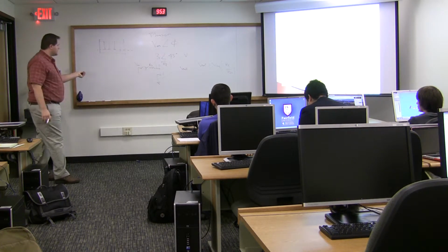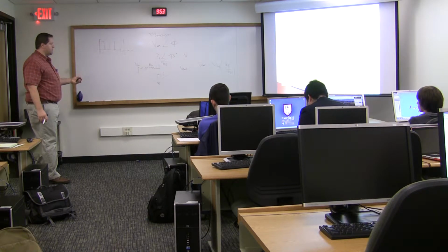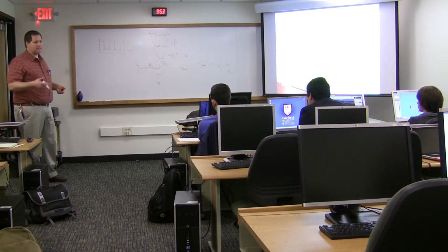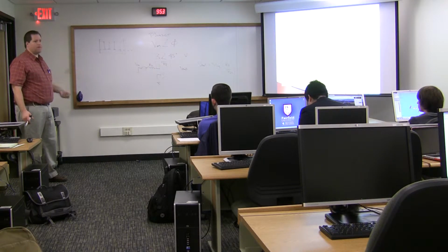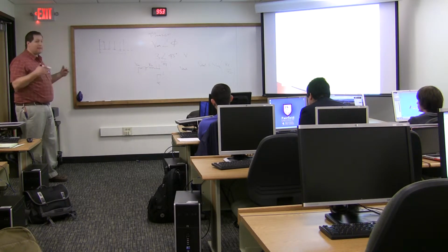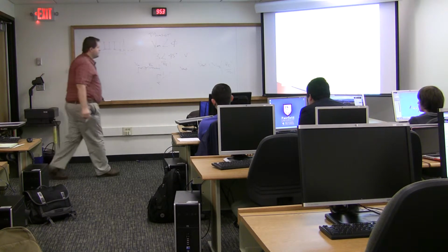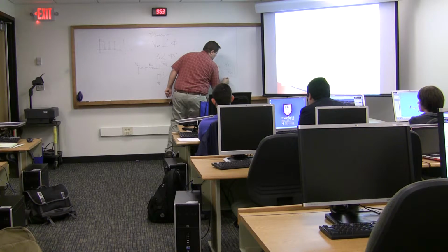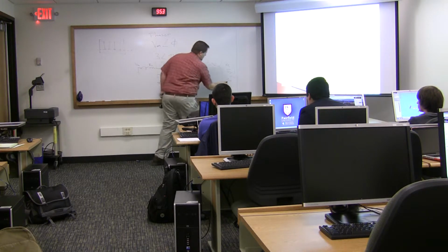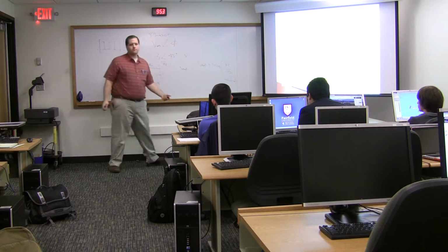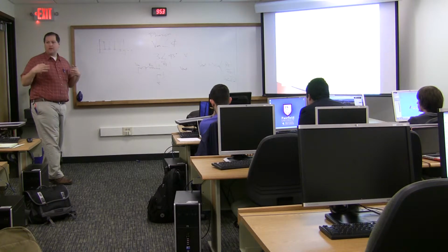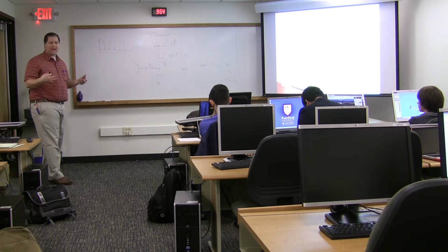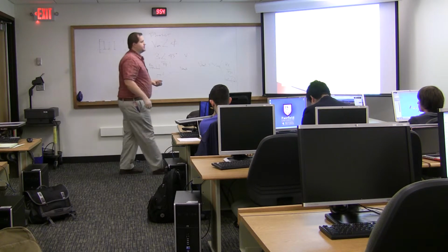In this case, we weren't necessarily dealing with frequency because this is just a DC voltage, but we saw this again with AC, right? We did these, but we defined a fixed omega. So the omega term never really ended up in the final form. We didn't really see it. But if we left it in there as a variable, guess what? This gain would be frequency dependent. It would be a gain of omega, right? A function of omega. And so we're going to formalize now how we treat this idea of gain at different frequencies for all of our circuits.